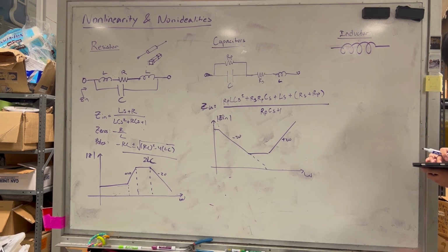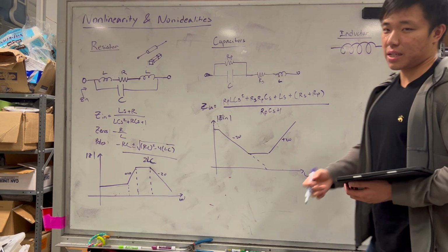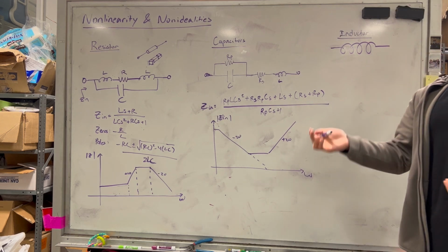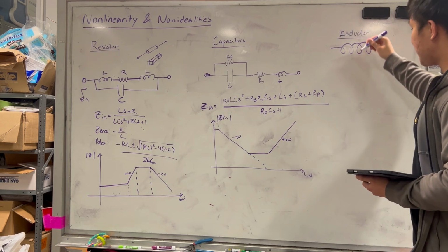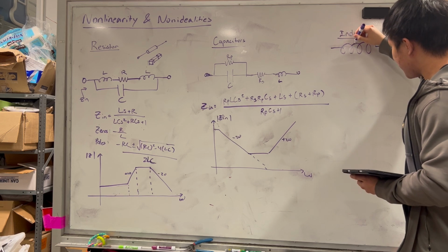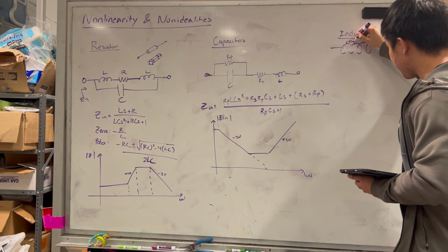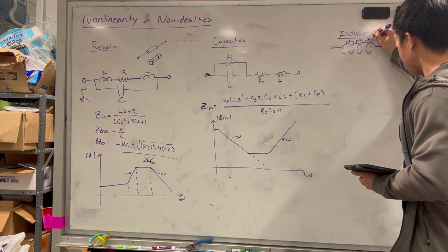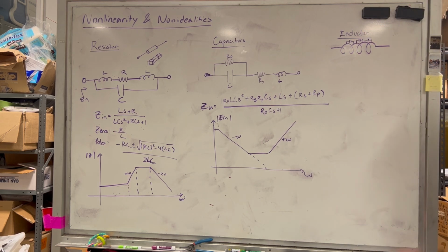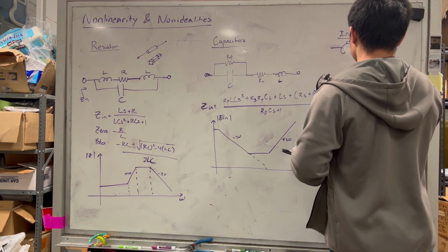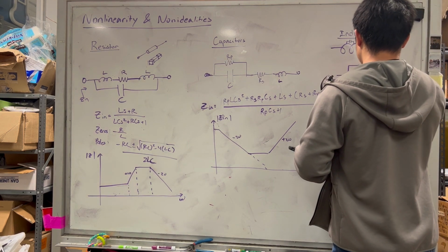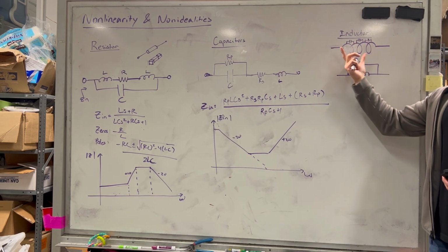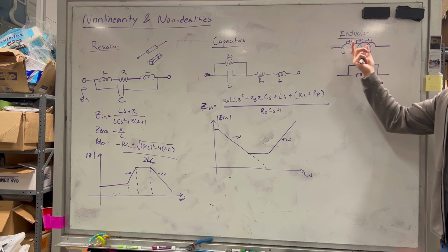But at the end of the day, what is a capacitor? Essentially just two plates of charge, right? But you'll notice that between here and here, there exists some capacitance. Between here and here, there exists some capacitance between these coils. And so you actually have an inductor with some parallel capacitance that goes across the inductor due to this effect. Does everyone kind of see how this capacitor arises?